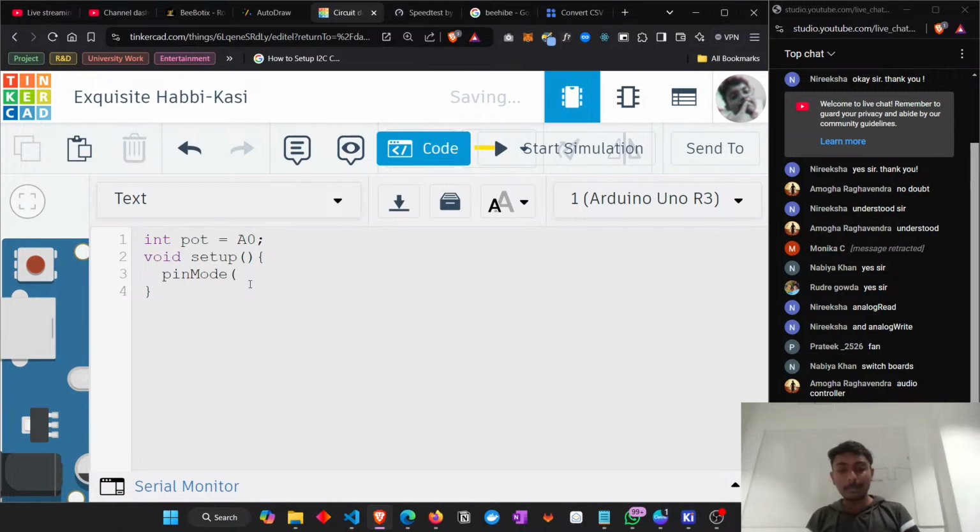Great. Now, pinMode again we will set pot. Pot is an input or output device? It's an input device. So I will type INPUT. Okay, done. Now void loop. Void loop means it will keep on repeating the same task which we learned in the past two classes.